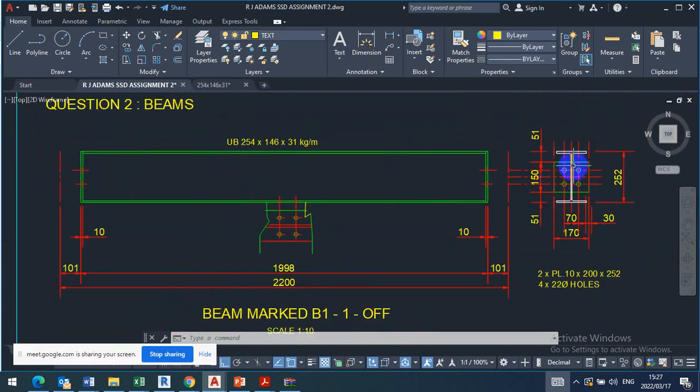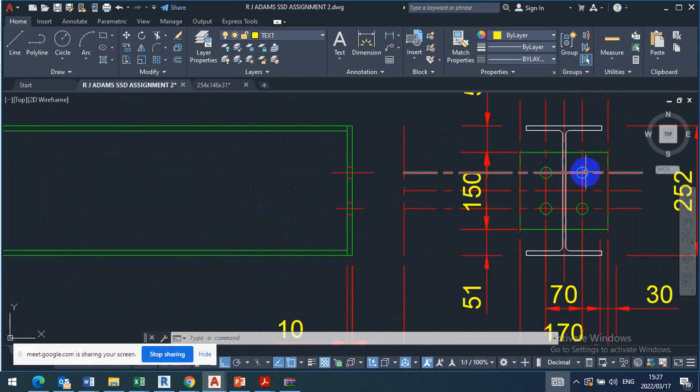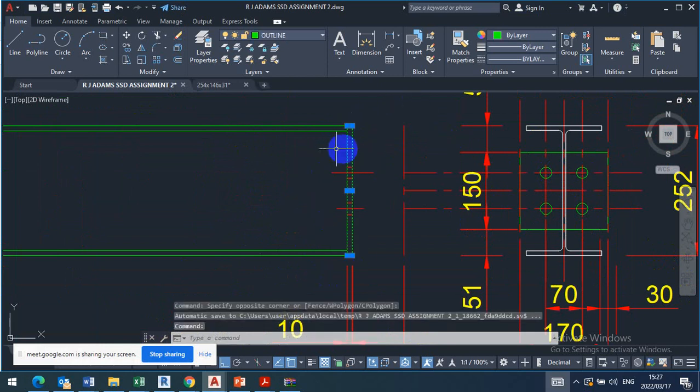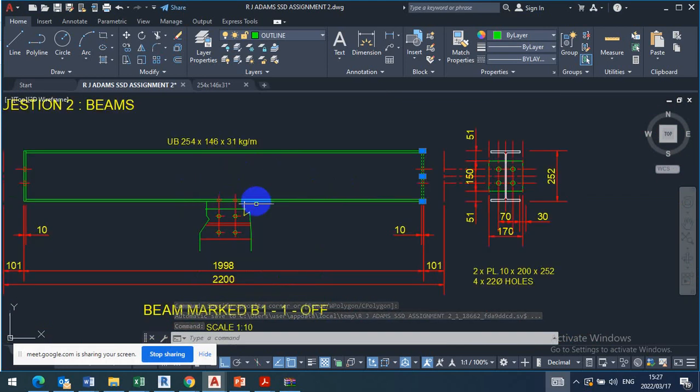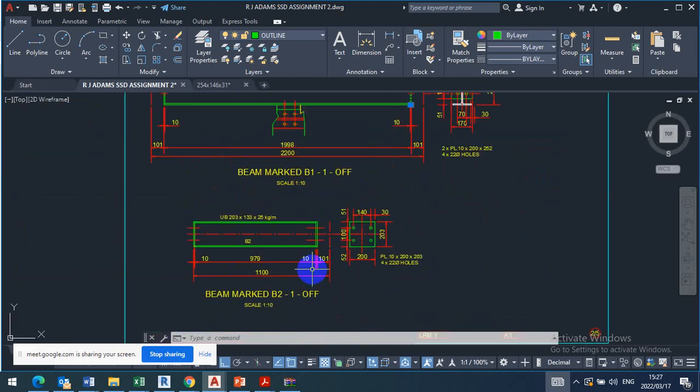But when we come to this side view, from here to here, we use the beam detail because it's the beam that comes with the end plate. Here, it's not the beam that comes with the end plate, it's the column. So that will also tell us which position the bolts are going to be drilled. It's according to the cap plate on the column. All right. Any questions?